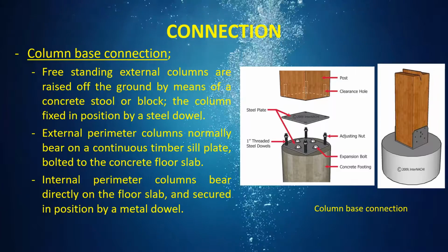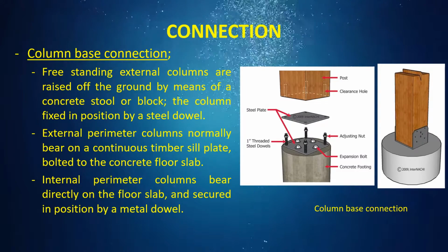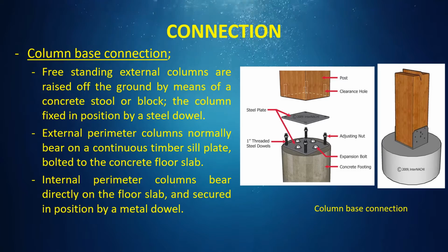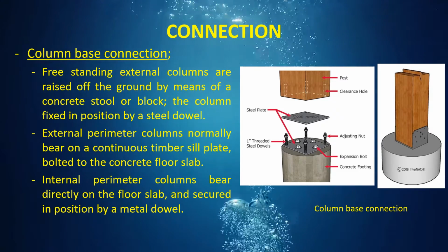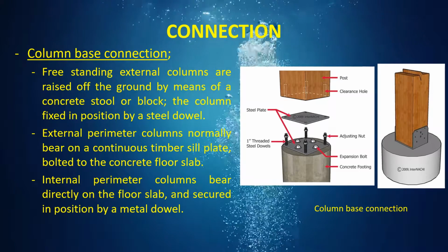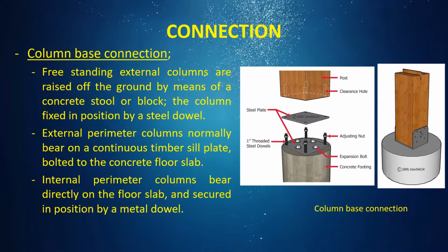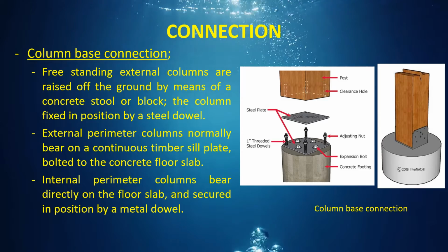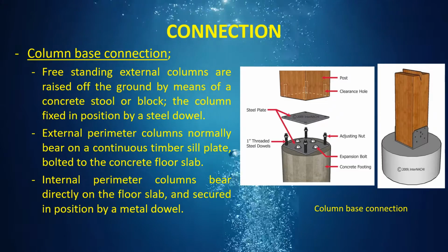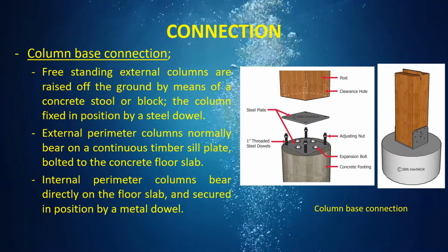Column-base connection. Freestanding external columns are raised off the ground by means of a concrete stool or block with a damp-proof layer between the timber and concrete. The column is fixed in position by a steel dowel or by straps and bolts.